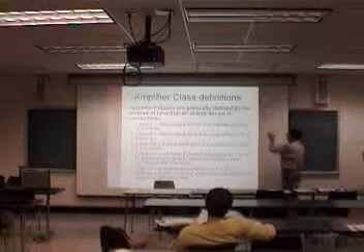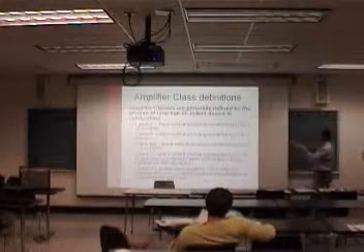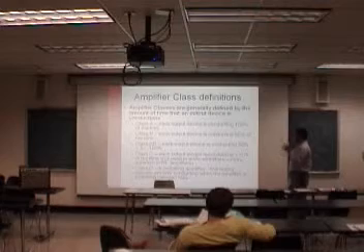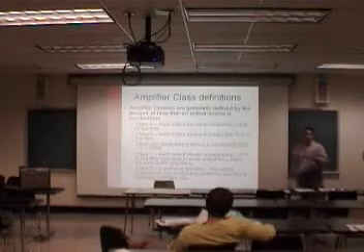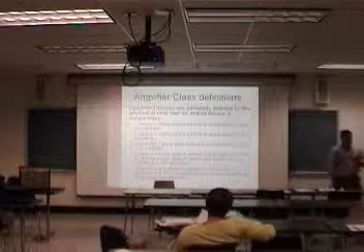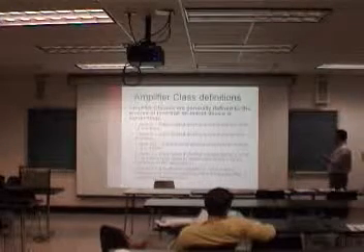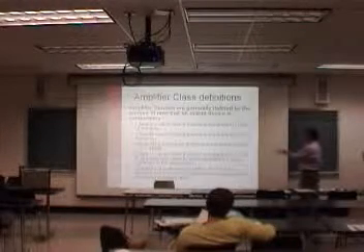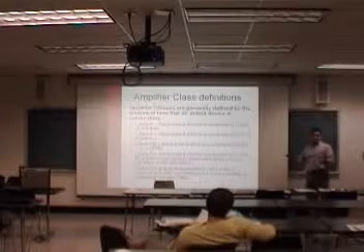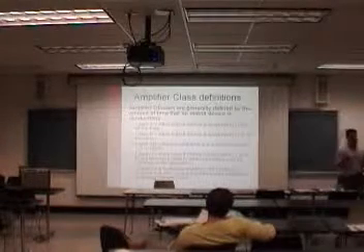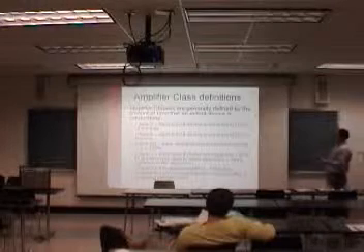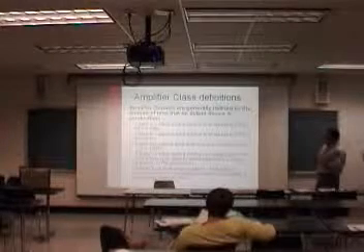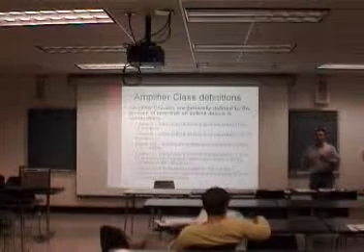So the basic definitions are kind of set in stone. They're very rigid if you look at it. Class A means every output device is conducting 100% of the time. Class B is you're conducting 50% of the time. And then Class AB says anywhere between 50 and 100%. There's some controversy over certain amps, like certain Vox amps. They're often described as Class A, whereas I've seen some analysis that says the output tubes are conducting maybe 80 or 90% of the time.